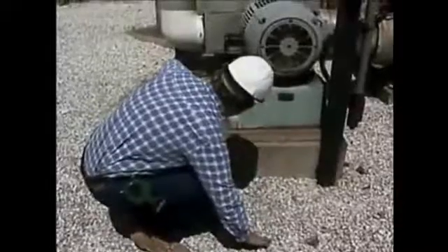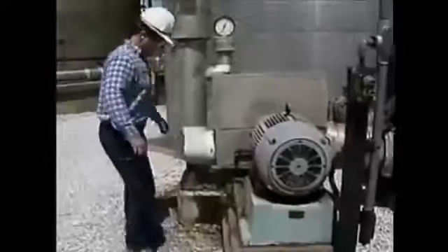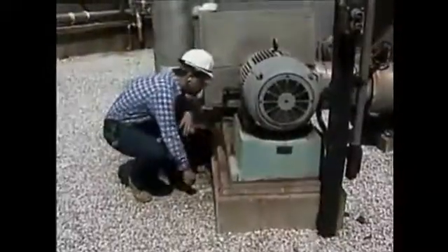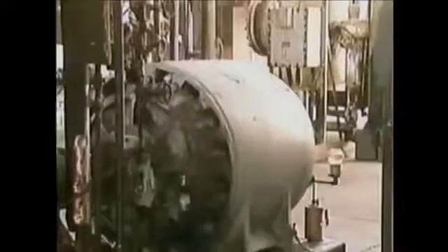Some motors use sealed bearings that do not have to be relubricated for the life of the motor. Other motors rely on a lubrication system to supply the bearings with grease or oil. If the motor uses a lubrication system, it's important to know how much oil or grease a motor is using. If the motor seems to be using an excessive amount of lubricant, check for leaks.